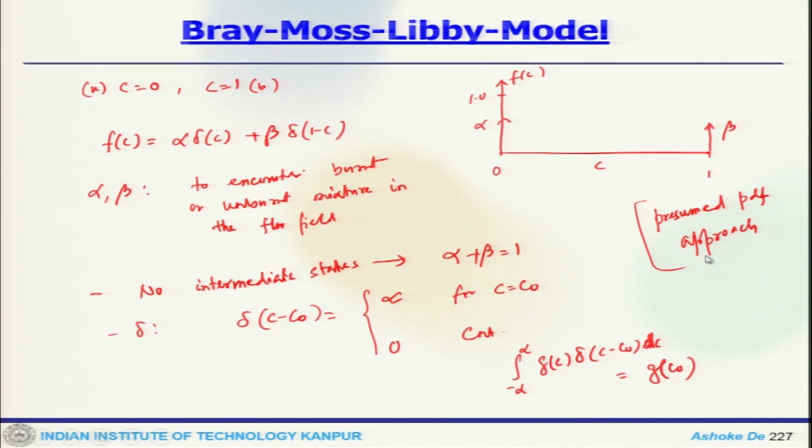But what we discussed, in hybrid combination like Lagrangian and Eulerian, that is a transported PDF approach where you have a transport equation for the probability distribution function. Here we solve a different transport equation, but assuming the distribution with an a priori shape of that PDF, and that is why it is known as presumed PDF method.